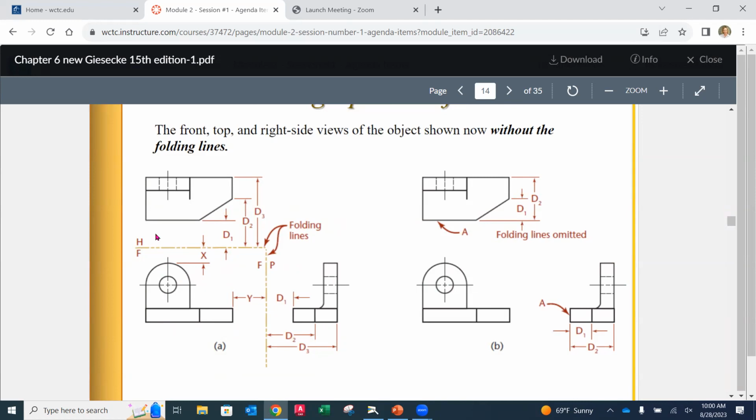Okay. Now, as we look at the front view, again, strategically picked to give us the best and the major shape of the part. So this looks good. Now, as we look at features, for instance, such as the hole that's in here, when we project straight up, and I'm using the center line first, projecting straight up, notice that it's in line with the center line. And then in this view, we don't see it as a circular feature. Instead, it would be looking down through the material here.